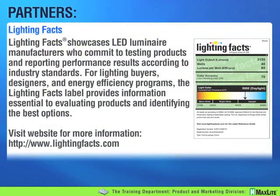Also, Lighting Facts. Lighting Facts is also a part of the DOE initiatives. Lighting Facts says that this product has been third-party verified, and here are the actual results from that third-party testing. MaxLite is proud to say that all of our LED products are going through or have been through the Lighting Facts process. Now, this particular product has an efficacy of 80. Another brand might have, for a similar product, an efficacy of 40. In other words, Lighting Facts doesn't say that this is a superior or inferior product. It just says that here are the honest-to-goodness specifications that have been verified by a set of third-party laboratories.